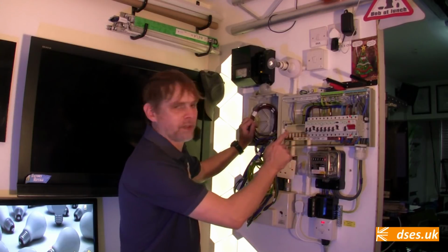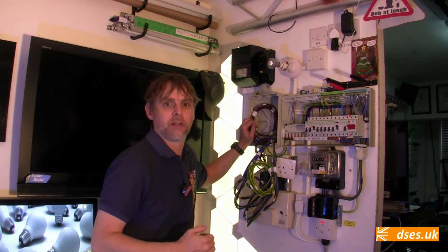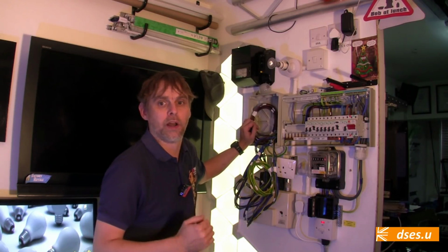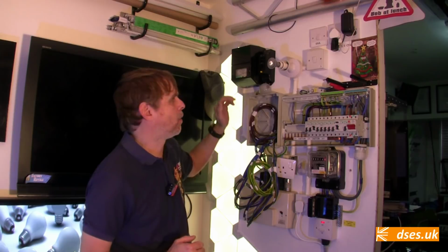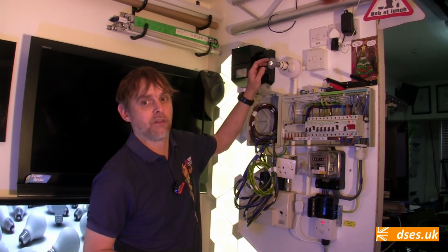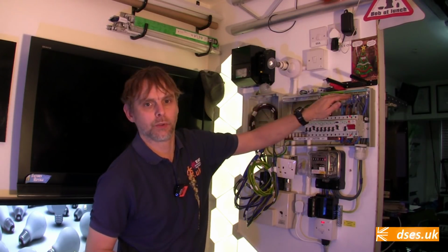It's flowing from the socket breaker down into the socket line wire, through the electric field created by the 230 volts AC on the socket line wire, and into the adjacent wire of the lighting circuit, where it then causes the sensitive electronics in this particular lamp to actuate with a visible glow of the LED elements as the current passes through the lamp to get to neutral.